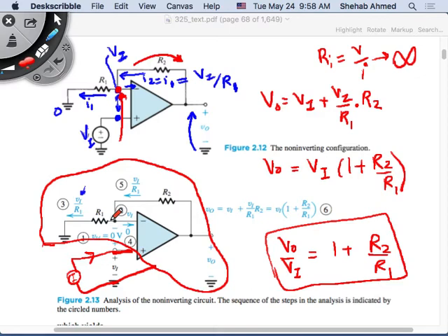I will not be asking the sensor to provide me with current to be able to measure, to send the signal through the amplifier. So it's a very interesting circuit. And the output impedance is measured the same way. So what is the equivalent circuit of the output? This is the op-amp equivalent circuit: a dependent source, a resistance if it's available, and ground. Here they didn't tell us it has an output resistance, so it's just a source.